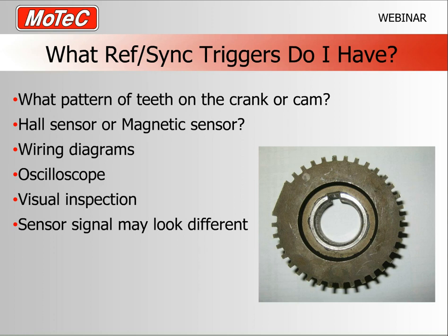is looking at the actual tooth profile. It might not be exactly what the signal looks like when it comes out of the sensor. So you just have to be a little bit careful. I get quite a few people ringing me, telling me they've got weird patterns, and from experience, I know they are not true. So at some point, you are going to need an oscilloscope, or luckily enough, with the 100 series or the M84 software, we have the ref sync capture program.